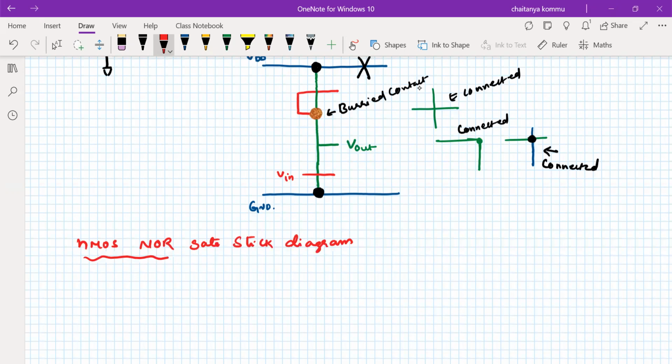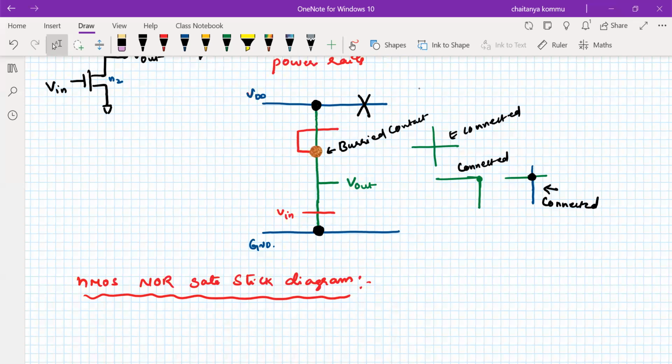By the way, if you want to have a NAND gate, for example, what I have to do is just use another transistor at the bottom. Here I need to consider another transistor, so we have to draw another red line here, that's all. But you have to give space between them. Don't write them very near to each other. For the NAND gate we just have to use 2 polysilicons. That's it. It will be acting as a NAND gate.